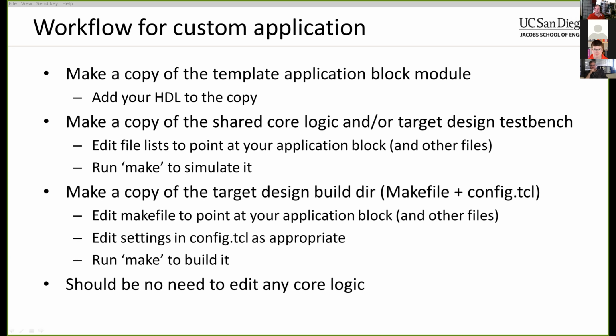Piece of cake. Now, this doesn't say anything about what's going on the kernel module side. That I'm going to have to sort out at some point, but I'm going to get the hardware side of things working first. But the idea is that you shouldn't need to edit any of the core Verilog code for Corundum. You just need to add your code in the application block and then point the Corundum build setup at that, and then you'll be good to go.